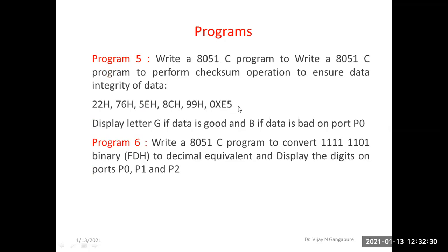if the sum is equal to 0, it means that the data is good. If the sum is not 0, then the data is bad, meaning there was an error while receiving it at the other end, and the data should be sent again. In this way we can check the integrity or correctness of data at the other end by using the checksum byte that is sent with the data bytes.